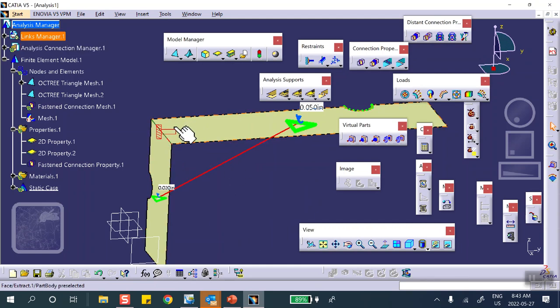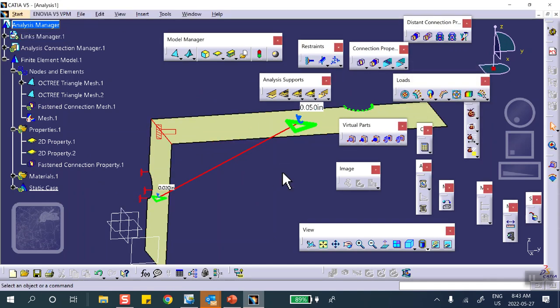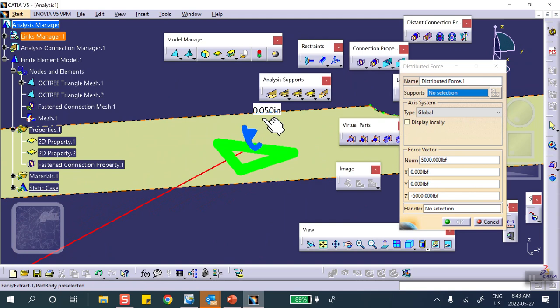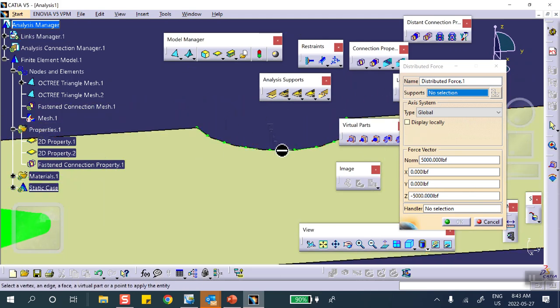Okay. All right, let's go ahead and clamp this edge. I think it says this edge is clamped. And then we push on the top by a force of 100 pounds. Okay? So let's apply a force on that edge. Now, if things are blocking your view, then you have to zoom in or hide them. I think there may be a sketch there. So I'm going to hide this. Too lazy to go. I'm going to hide it.